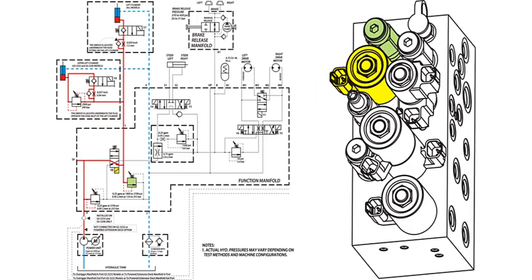When the lift function is selected, solenoid Y8, highlighted yellow, is energized, directing 100% of the pump flow to the lift cylinders. Pump flow is allowed to bypass the orifice restriction, and the holding position of valves Y7 and Y9. Vent hoses, drawn on this schematic with dashed blue lines, allow any fluid that may pass the piston seals to return to the reservoir. They also prevent vacuum while the linkage is being lowered. Y7 and Y9 hold the cylinders in position when the lift function is deselected.